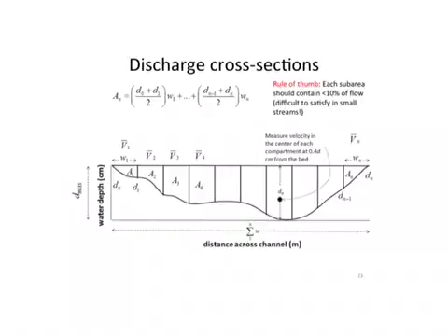So this is just showing how that equation would look when you do that over each one of the polygons within this stream. In this particular diagram, we're measuring a mean velocity, which we just often assume is the velocity measured in the center of each one of these polygons. So Q here would be equal to this incremental area.